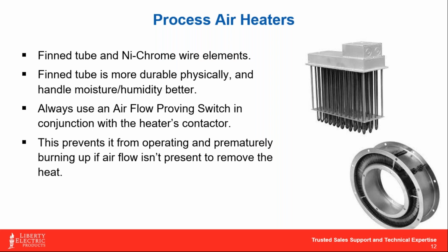The one thing I would definitely stress with air heaters as well is you'll always want to put an air proving switch in line with your process. What an air proving switch does is look for positive air pressure, so that you couldn't have a situation where the heater is running and there is no air passing across the element, because that will burn it out. Just like we talked about with that cartridge heater, that buildup of heat has no place to go. So we either have to put it against a solid and transfer that heat, or we push air across it to cool the elements. So it's very important to use air proving switches.